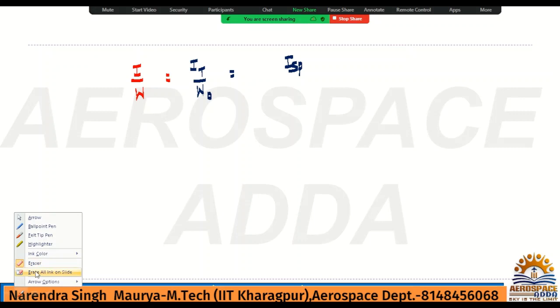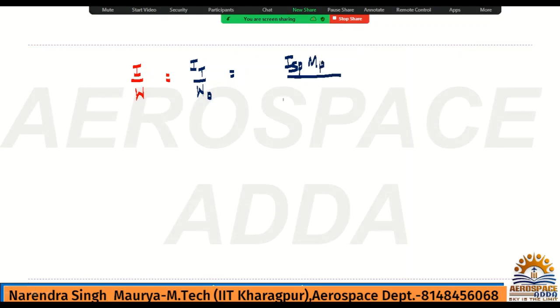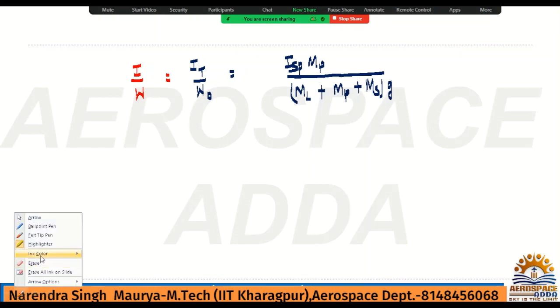Check it, I am saying total impulse. So ISP into mass of propellant divided by W naught, which is the mass of the payload plus mass of the propellant plus mass of the structure, and G. All right, so this formula is very important. This is called the impulse to weight ratio. Okay, so I'll put it in a box.